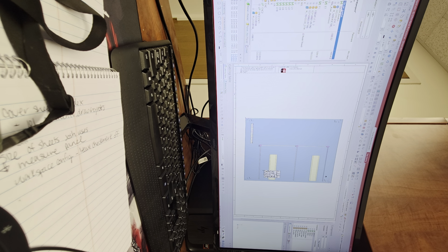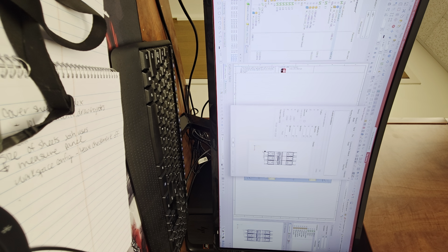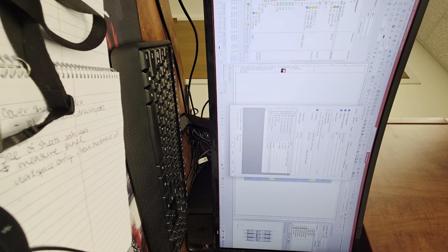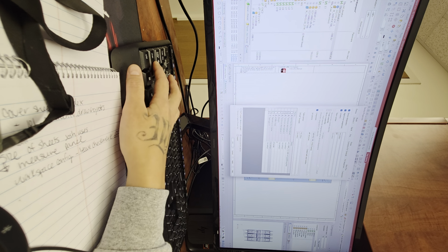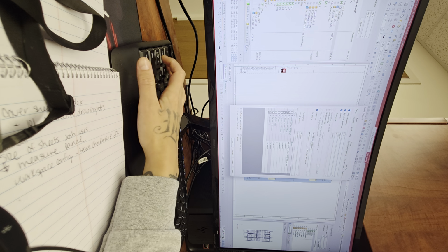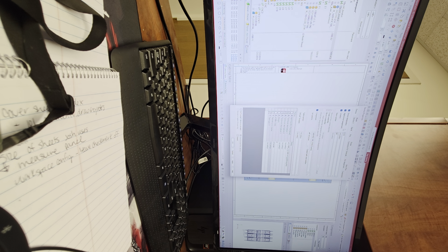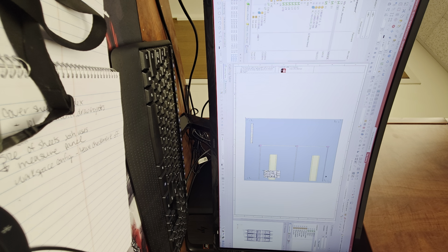So right click on this green item, then device properties. Click on the devices tab. That's where everything kind of starts. Normally in the projects this will be referred to like a CB1, circuit breaker 1, from a reference perspective. All references are capital. So this will be the normal, standardized, project usable name, if you will. Click apply and OK. So that will fix that.